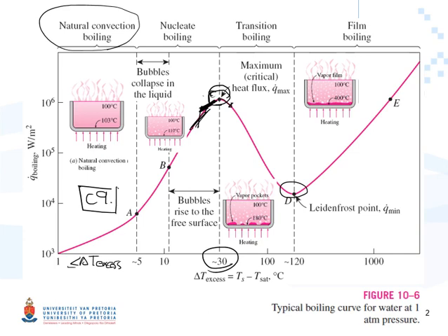It's very important to keep in mind that a little bit less than C is much more desirable compared to a little bit after point C, because with less delta T excess you are getting exactly the same results. Of course, it's very difficult to control the temperature in a way that you are exactly at point C and the maximum all the time.